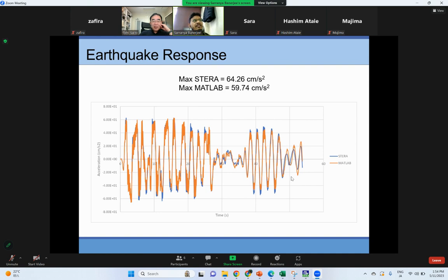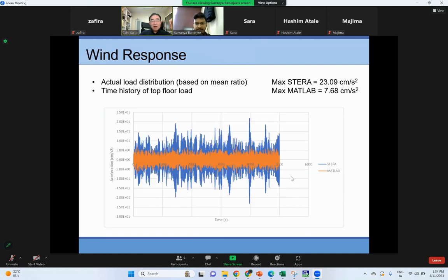In case of wind, because wind is very small, the first stiffness affects the result much in case of bilinear. Yes, so I think your result is reasonable. You should check the hysteresis of the isolation layer. Yes, I believe wind must consider the hysteresis. Response may be different. But for earthquake, I'm also interested in the hysteresis of the earthquake response.